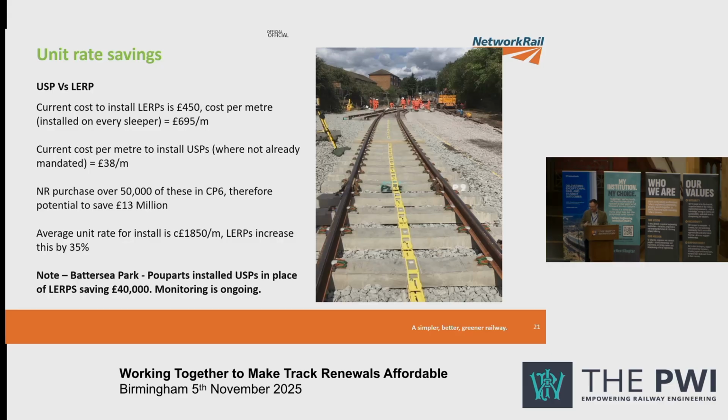And this is the statement of why not use undersleeper pads? They have the same lateral resistance. Yes, there could be a void there, but there is an allowance for void in the CRT value. If you get track voiding, you deduct a certain amount. So we know that is the case. But by putting the USP on from the start and installing it from the get-go, then we get that improvement straight away. And we don't need to keep adjusting it when we need to go in and tamp. Every time we need to tamp, we have to bring up the anchors and put them down again as well. Then they get left off, and then people tend to say, okay, we're not going to use them anymore. So at least this is a permanent fix.